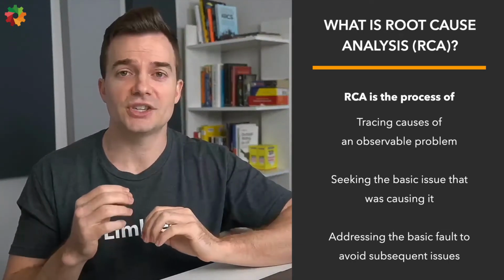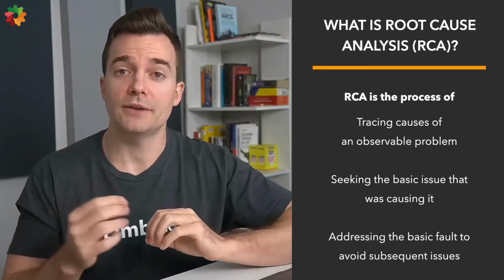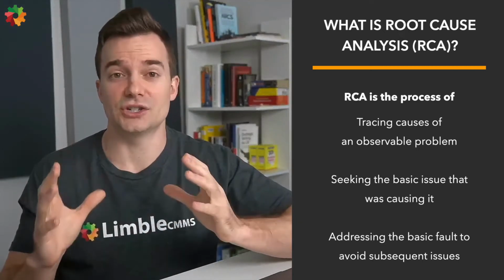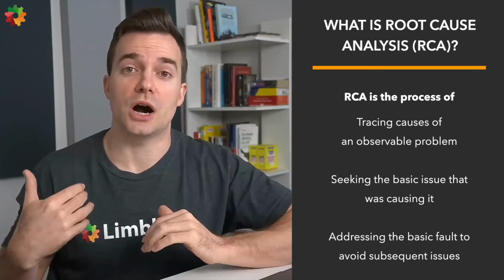For example, imagine a scenario where a machine stopped because it overloaded and the fuse blew. A brief investigation shows that the machine overloaded because one of its bearings had an issue. So substituting the bearing would probably allow the machine to go back into operation for a while.